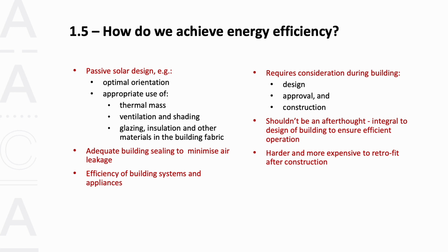sealed, since all the warmth inside the building in winter will escape and unwanted heat will enter the building during summer. Good building sealing means that if you use energy to heat your building, the warmth will be retained for longer inside the building, and so the building won't require as much mechanical heating. Ditto in relation to cooling the building. So all of these factors listed and others have to be considered at the design stage when it's cheaper and faster to ensure that the building will function well for the climate zone.